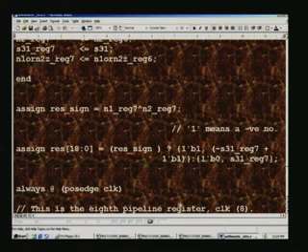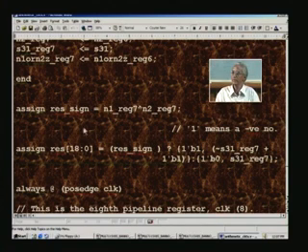That is what we need to register, which we will be processing with the arrival of the next clock, and before that we will do the computation if there is any. Let us see what we are doing here. First, we have been propagating the N1 sign bit as well as the N2 second number sign bit all along. If you take the exclusive OR, you get the final result.